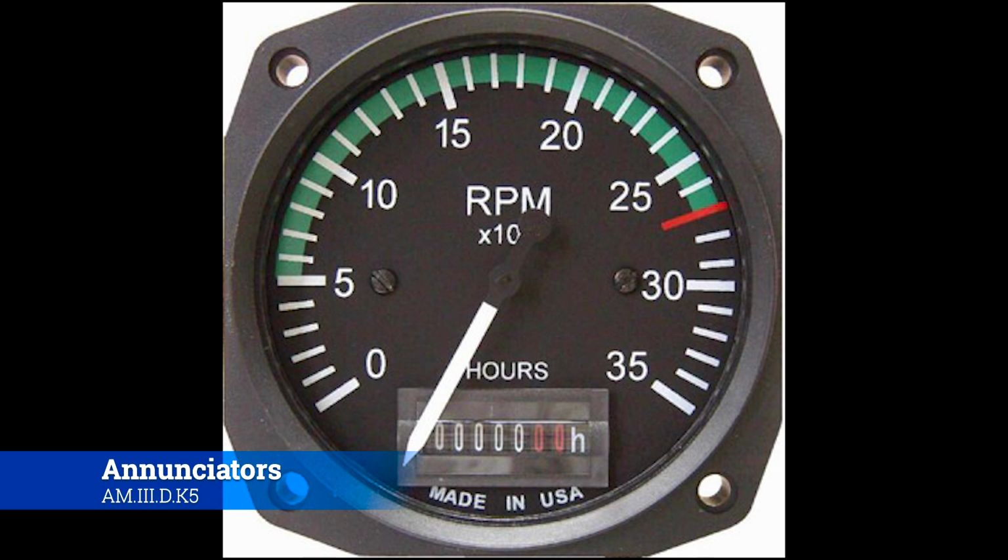As a maintainer, you're going to follow suit and say, at max power, I'm going to go full throttle. How many RPMs do we have going? If it's in the range, cool. Then you go and say, okay, how's our oil pressure look? How's our fuel flow look? How are all these other downstream things? If it's not right, then those downstream gauges are going to tell you it's not right because we don't have the fuel pressure, or because the oil is acting up, or whatever. So this is kind of the first block on the flow diagram of troubleshooting: what's our RPM at, and why isn't it correct? But yeah, that's your RPM gauge.